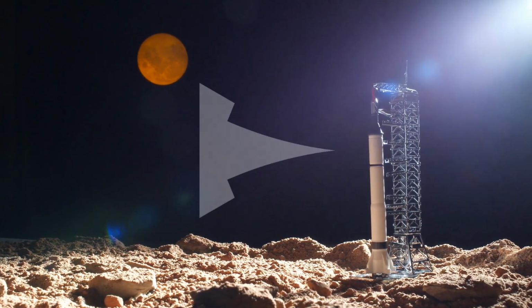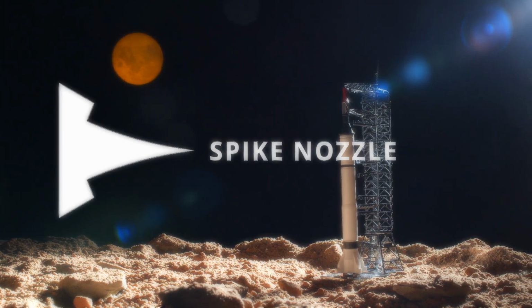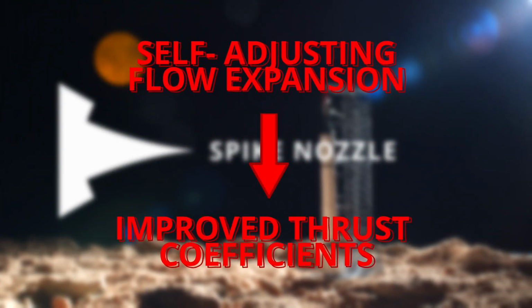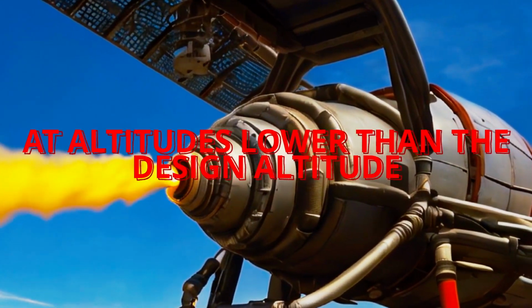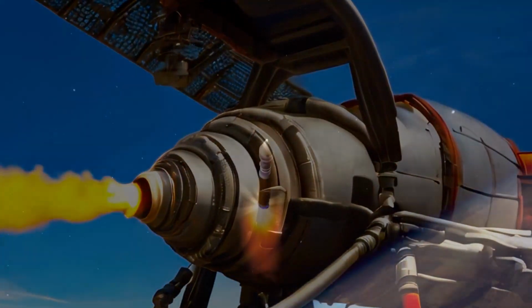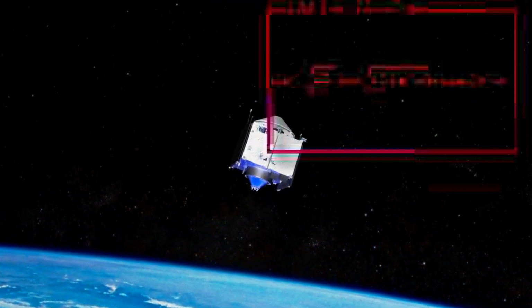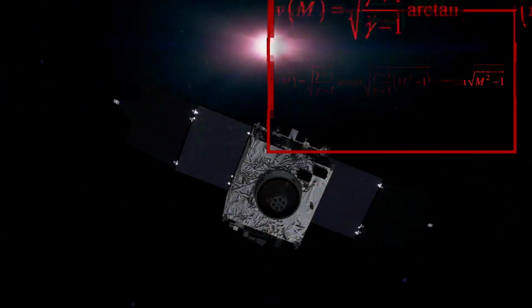Unlike conventional bell-shaped nozzles, which operate optimally at specific altitudes, spike nozzles offer self-adjusting flow expansion, resulting in improved thrust coefficients. This enhancement is particularly noticeable at altitudes lower than the design altitude. The design methodology for a spike nozzle adopted is rooted in the utilization of the Prandtl-Meyer function, assuming ideal thermal and calorific properties of the gas.